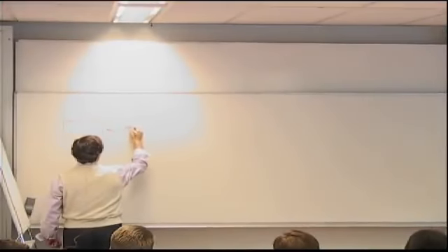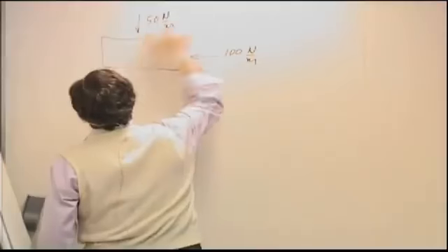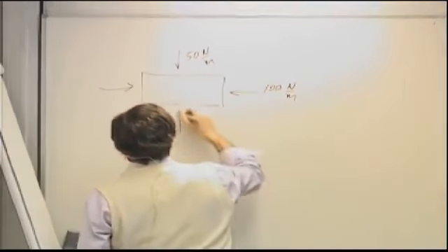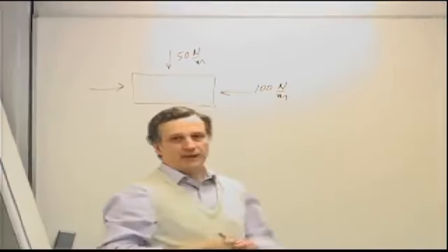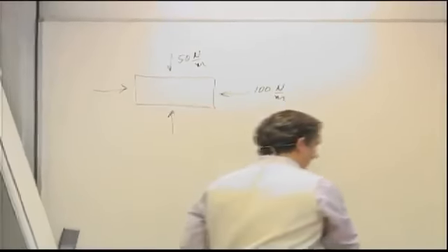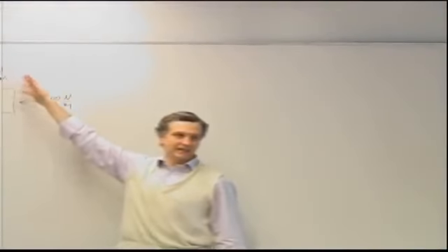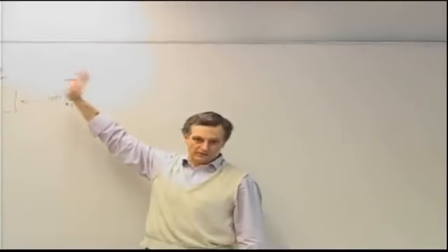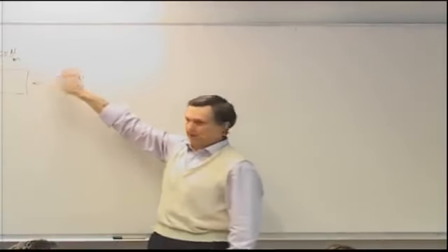Let's say this is 100 newtons per meter, and this is 50 newtons per meter, and I'm asked, find the buckling load. Now, there are several possibilities here. First of all, the plate may have already buckled before I reach these loads, or it may buckle beyond these loads. It's highly unlikely that the applied loads given to me or that I determine somehow are the buckling loads themselves.